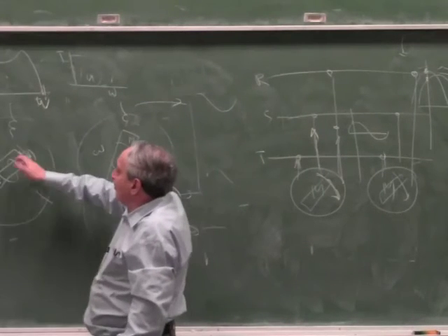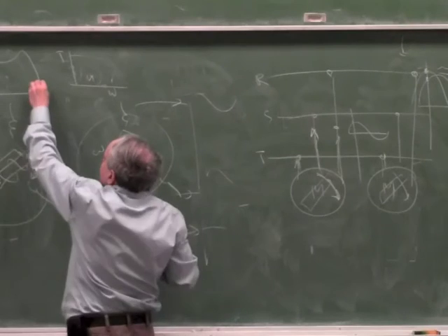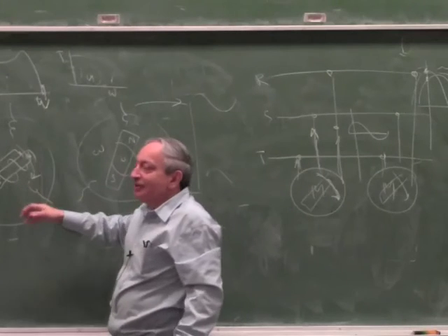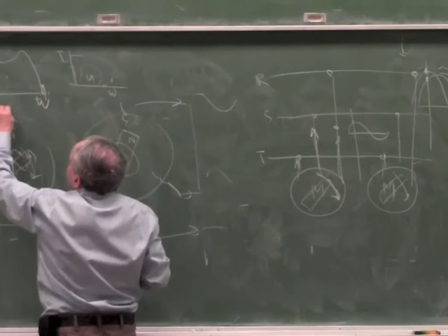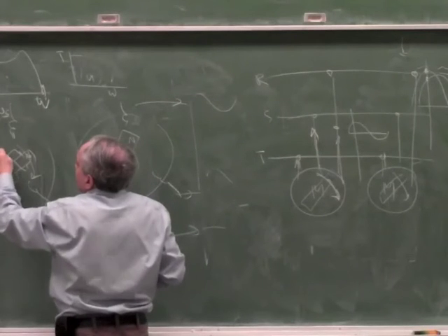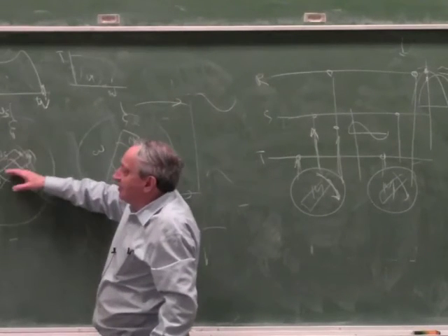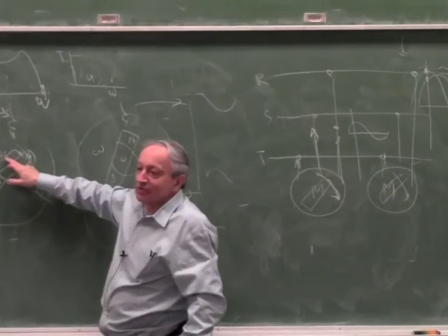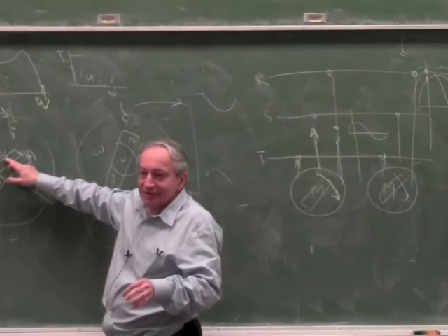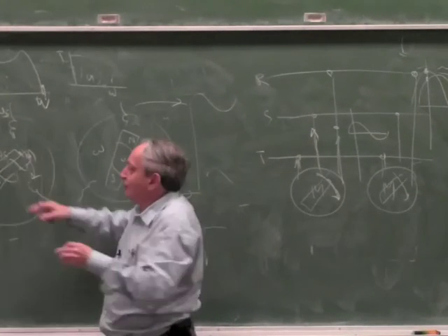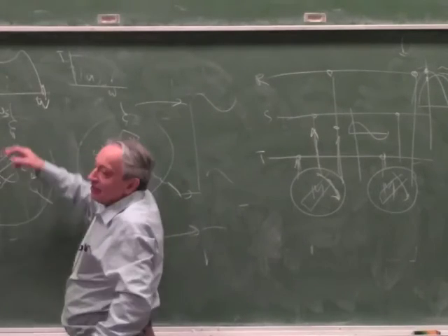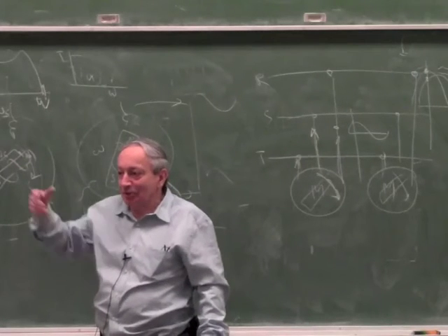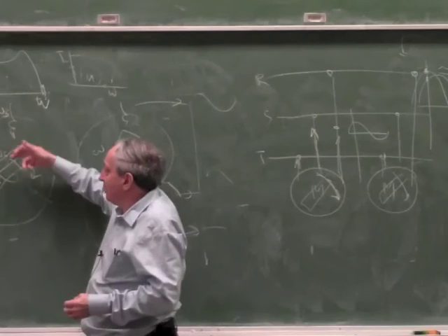So if you force this to go at the synchronous speed, then no power will be transferred, because it doesn't work as a transformer. If this is omega synchronous and you force this to rotate at omega synchronous, it sees a constant magnetic field, because they're both working together. If it sees a constant magnetic field, there is no induced current, there is no power going into the motor. So the first part is easy to understand. If you force this externally to follow the rotating field, no power will be transferred into the motor, except losses, but actually no power will be coupled to the rotor.